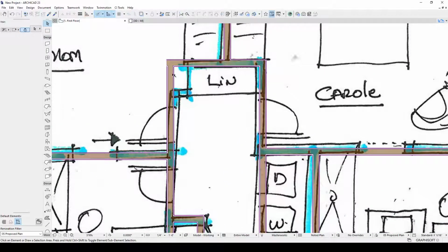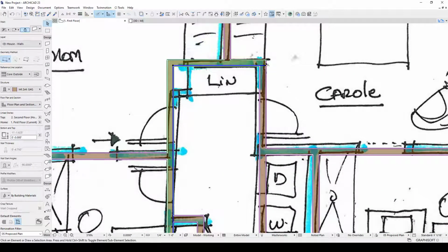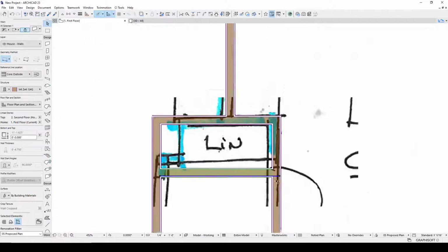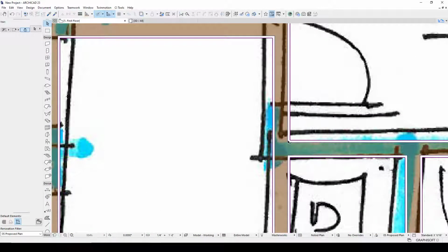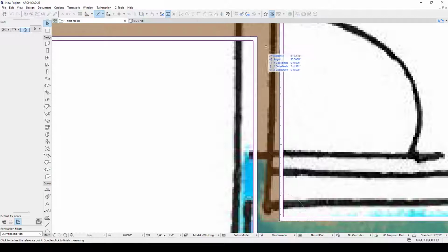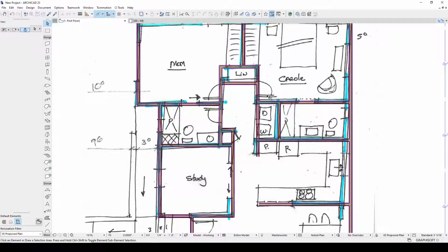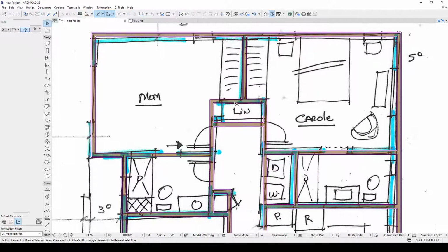I have a linen cabinet here. These need to get intersected. Bring this down. Make that a 2-foot cabinet. Need to make sure I have enough room. I'm hitting M for measure. 2'5", a little tight. And so this is where we start needing to design. I'm going to use the marquee and F8 to slide all of this up, and I'm going to give myself 3 more inches to get these doors to work in here.